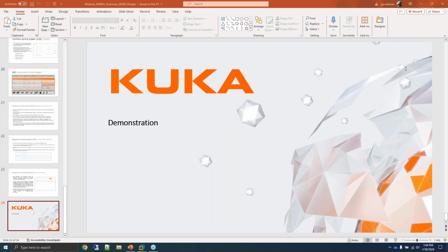How does the vehicle respond to an obstacle in its path, Joe? So you have the ability on an edge to determine whether the vehicle uses obstacle avoidance or not. Meaning, if there were a pallet, for instance, sitting in front of the robot, and you have configured the edge such that obstacle avoidance is enabled, the RCS, the robot control system, will attempt obstacle avoidance.